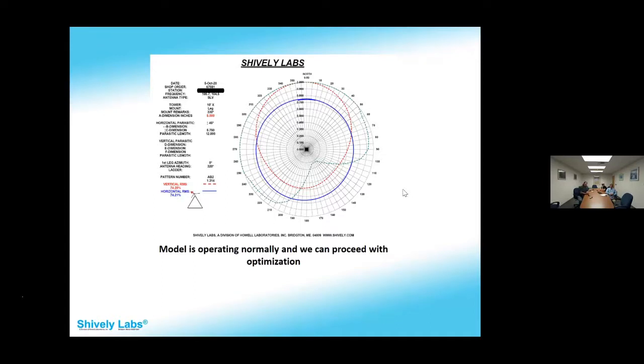And I think we've seen a presentation recently where they couldn't measure the far field because of the amount of elements in the array; far field was so far out as to be beyond the flight plan. And they had to extrapolate, they had to measure near field with the drone. And it matched the predicted near field from HFSS. And there was a way to prove that the far field was doing what it was supposed to do. This was another manufacturer, a television presentation that I watched.